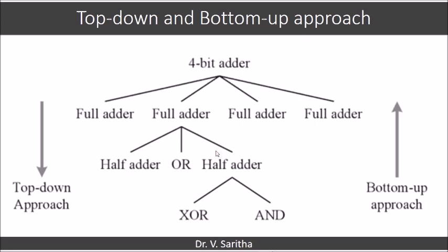In order to construct a 4-bit binary parallel adder, 4 full adders are required, and in turn every full adder requires 2 half adders and an OR gate. Similarly, a half adder requires an XOR and an AND gate. If we come from top to bottom, we call it the top-down approach, and if we go from bottom to top, we call it the bottom-up approach.